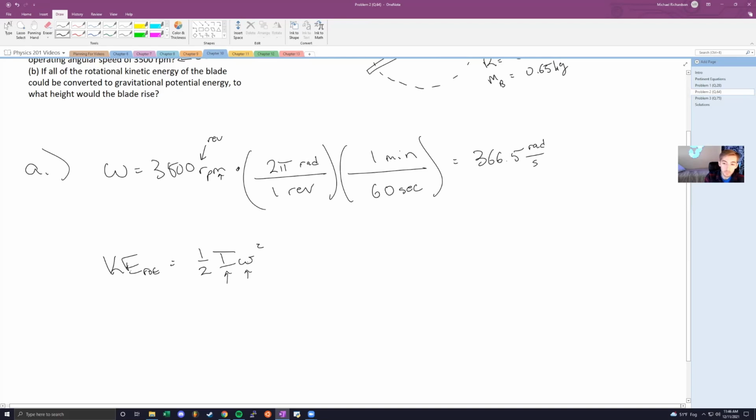We know that our moment of inertia is something we just defined, where we have both its mass and its radius, or distance from its axis of rotation. And it's just a matter of plugging the constant in front of it. So doing our substitutions, we get that this is 1/2 mr squared. And then our angular velocity we'll just keep as omega for now and plug in all of the rest of the values in the next step.